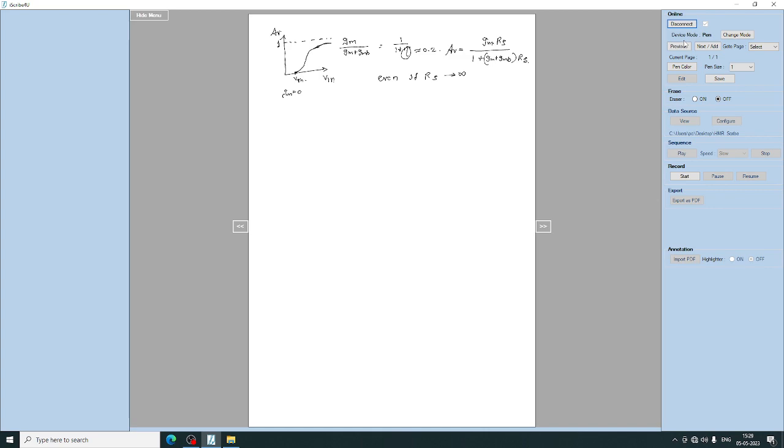In the circuit, if you observe, the transistor does not enter the triode region if Vin is below the threshold voltage, right? This is another observation we had to discuss in this common drain or source follower circuit. Continuing this, we will solve one problem on the same.